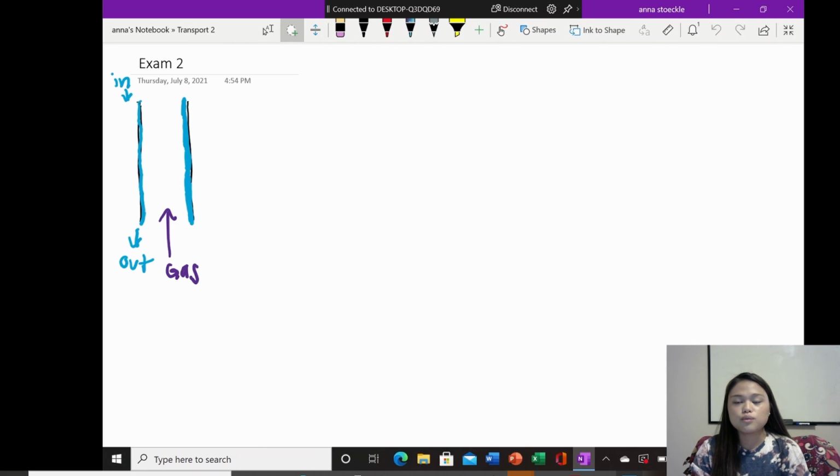So what we want to do is collect experimental data, but before we do that, we want to perform a dimensional analysis so we can reduce the dimensionality of this problem. And what we're going to be doing now is establishing that the Sherwood number, the Reynolds number, and the Schmidt number are going to be good dimensionless groups for this problem. So let's get started.